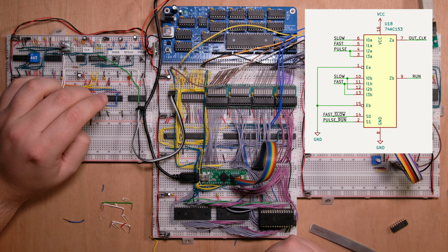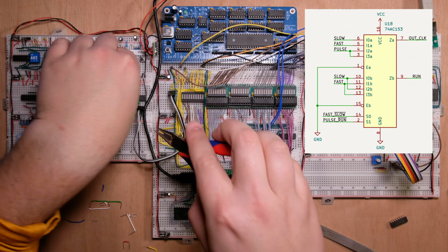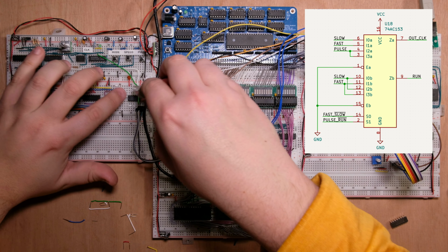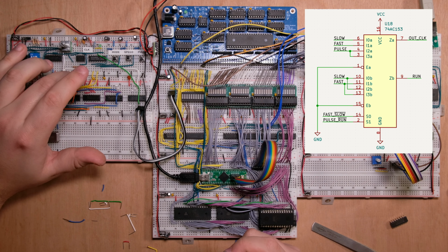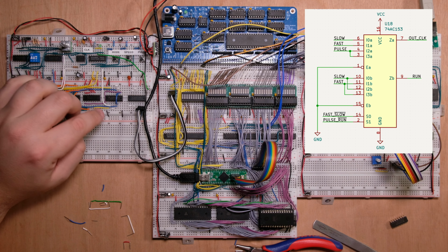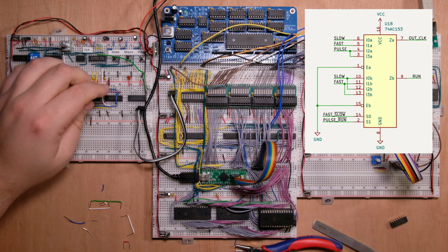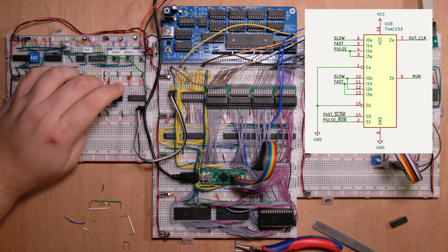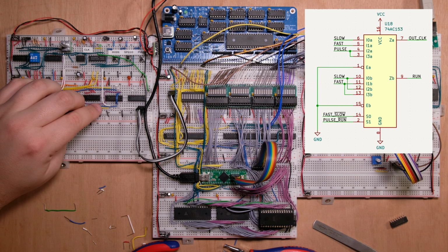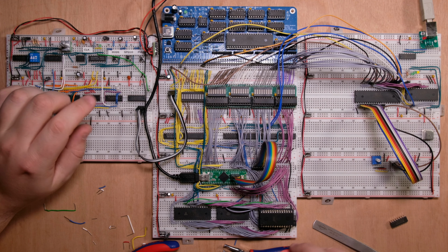Then we're going to need to connect 10 to 12 and 11 to 13. There we go. Then we need the pulse clock on pin 3 and 4. That's the white wire coming here. There we go. And finally, the output clock is on pin 7, and it goes to pin 4 of the output multiplexer. Okay, so these are all the pins of the 153 connected, and now we can do the output multiplexer.